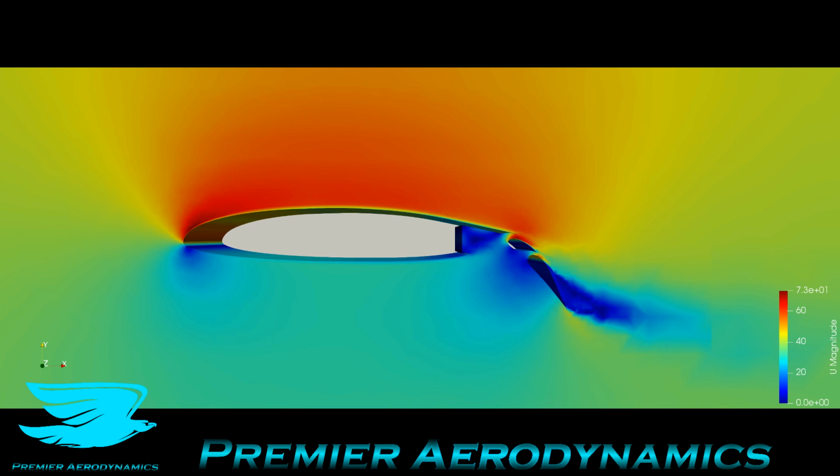However, it is producing quite a bit of drag, but it is still producing a little bit of lift, but not efficiently. That's why we get such a high lift coefficient, but a high drag coefficient as well. We can reduce the lift coefficient, but then that would reduce the drag coefficient as well. But if you want to get a lot of lift, you have to go into this configuration.